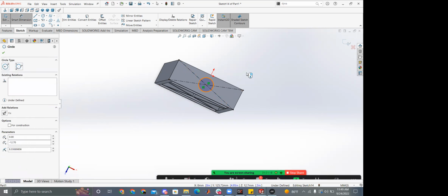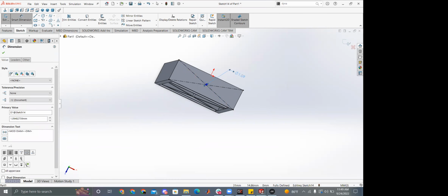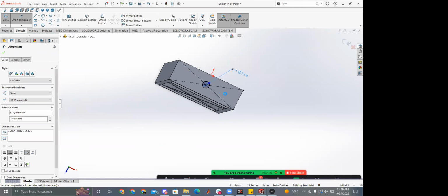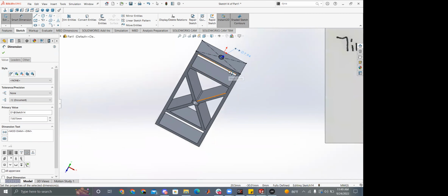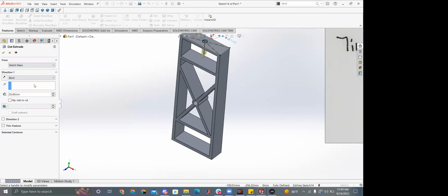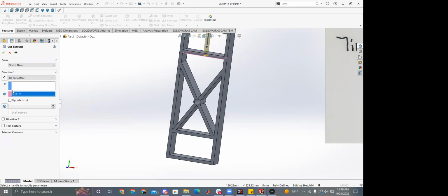We set the radius. Let's say we're going to mount with 5/16. Okay, did it again. That's why. We can mount with a 5/16 hole. So we have that hole centered on the top. We can do extruded cut, and of course we want to do the up to surface, right? And select this bottom surface. So it cuts through both of these.